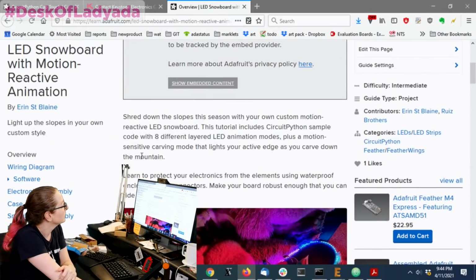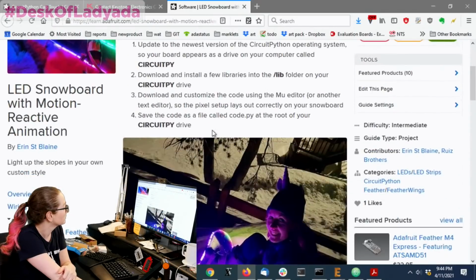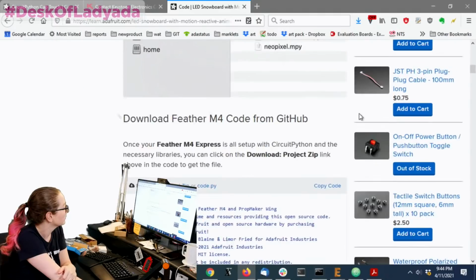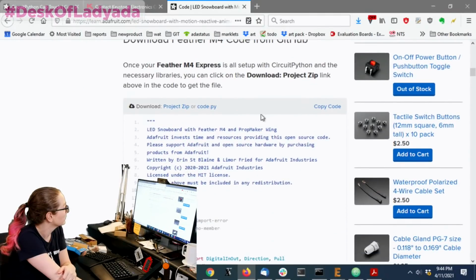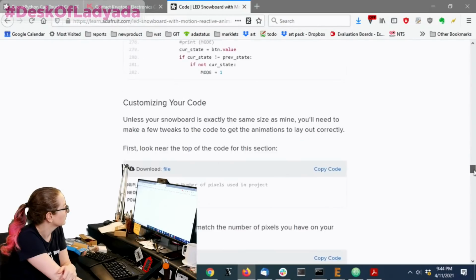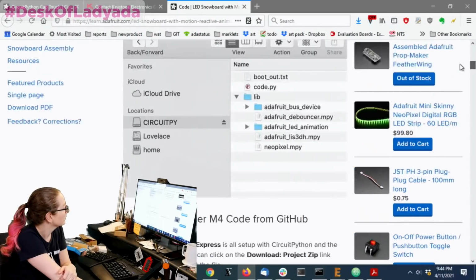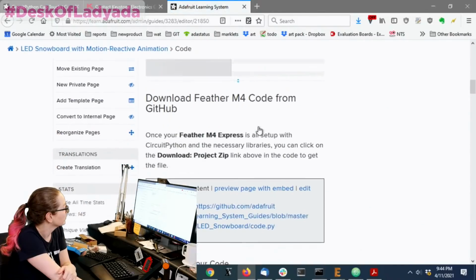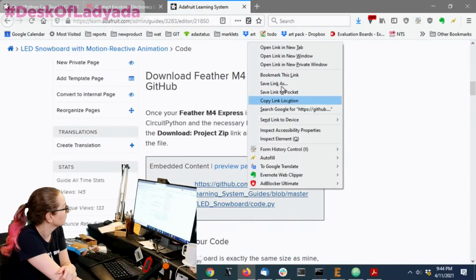I would freeze my projects. I would take all the files off my CircuitPython drive and move them to a folder on my computer, and I would zip them. Or I would just name them with the time and date, and it would have code.py, all the libraries and all the dependencies. And I knew if I had to in the future, I would just zap my CircuitPython device and toss it back on there, and those are all the working project files.